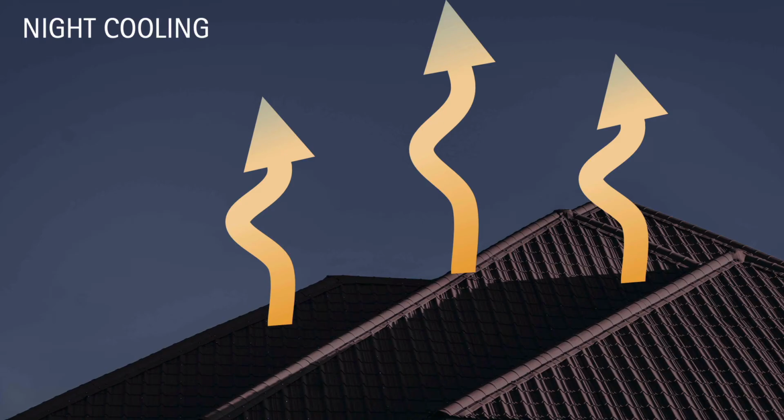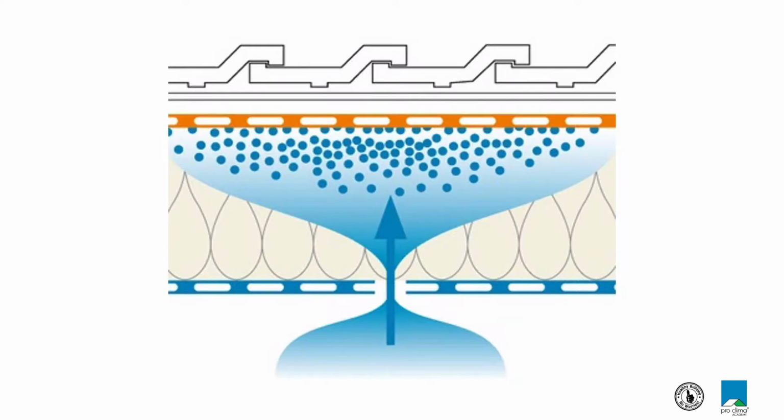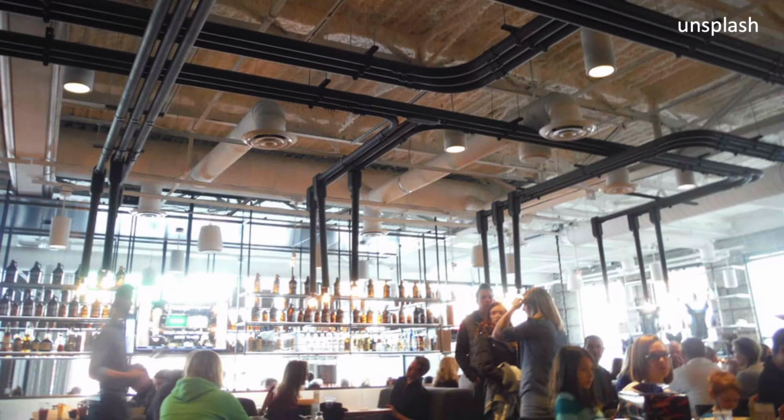the sky can induce sub-zero temperatures at the surface of the roof, even if the forecast and the air temperature is above zero. Now, this is obviously going to cause problems if we get any air that has moisture in it getting into that roof space, and that will happen wherever we don't have an air tightness membrane on the inside. And that's best case scenario. Of course, in a lot of roofs, particularly in commercial buildings, we don't even pretend to have a ceiling. So even if we do have a suspended ceiling in commercial spaces, or even in most of our houses, there's so many holes and perforations that we don't really have an effective ceiling that is preventing moisture-laden air from reaching the cold surface of the roof.